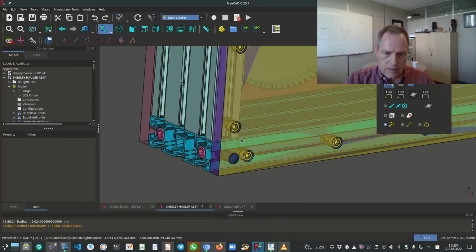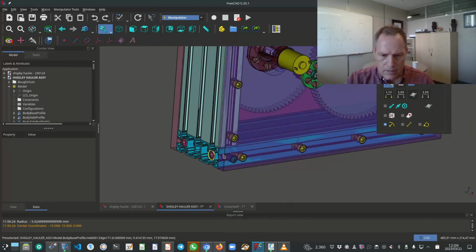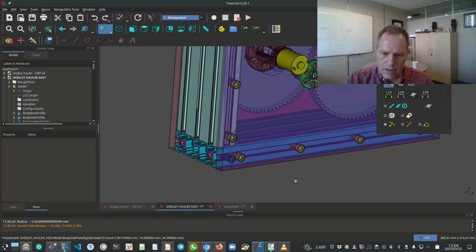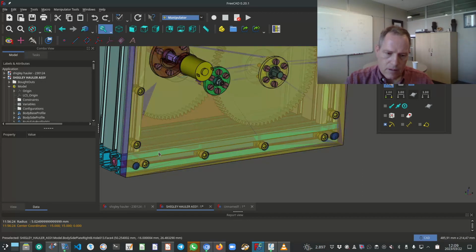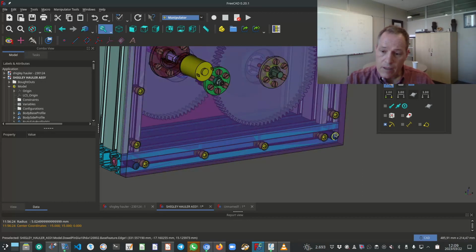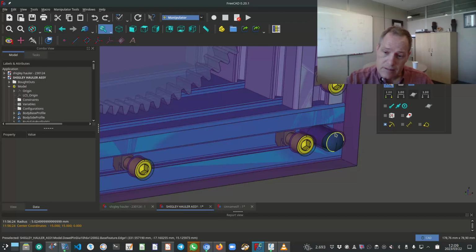The idea of the dowels is to align the 2 side plates on either side, and for the distance between the dowels, if there is variance in that distance, we can accommodate that, because on the one side we've got a slot.